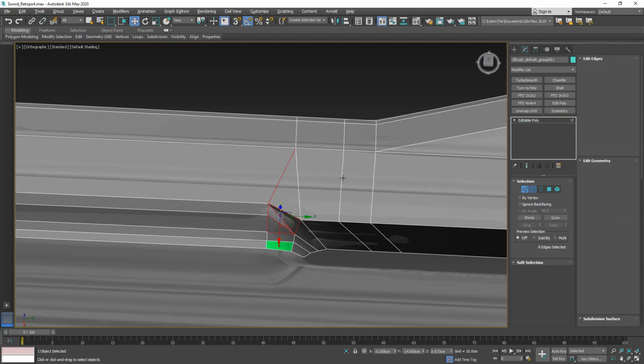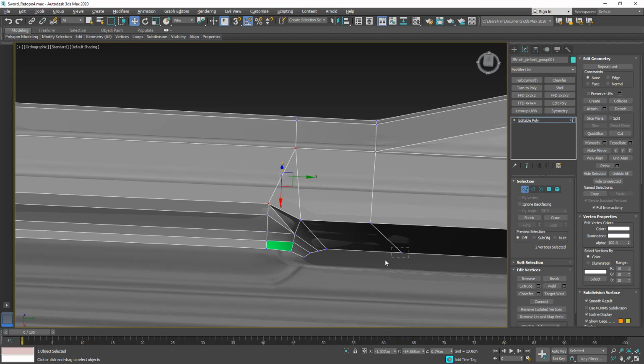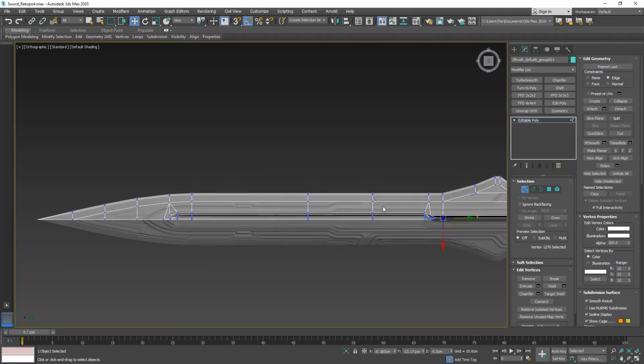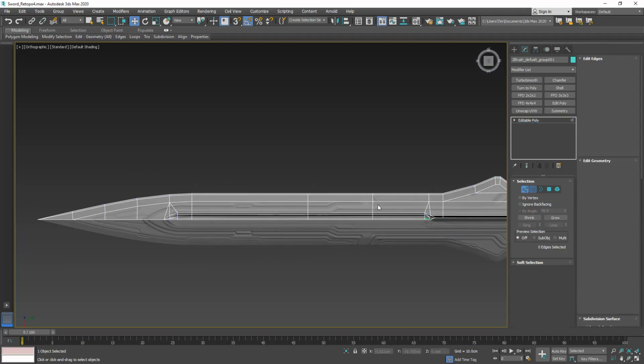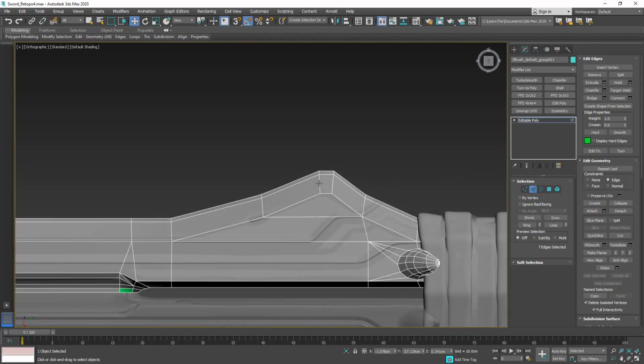And then let's switch over to our edge mode. And this loop, I'm just gonna Ctrl+Backspace, get rid of it. And then let's make sure that this here is somewhat aligned. Just gonna push that. And back to our edge mode. I'm gonna make a ring selection here, and then let's collapse it. And then while we have edge constraint on, I'm gonna push that over here so that we have it in the center.